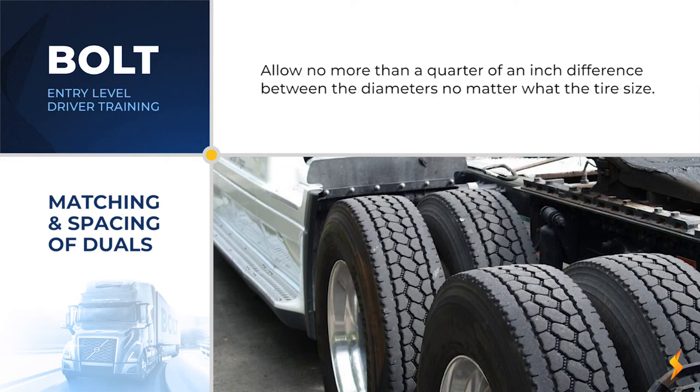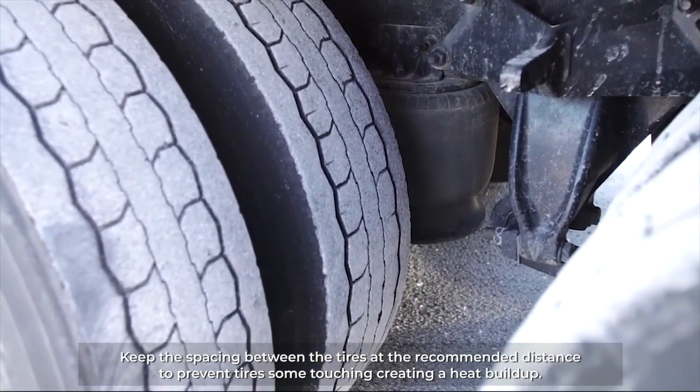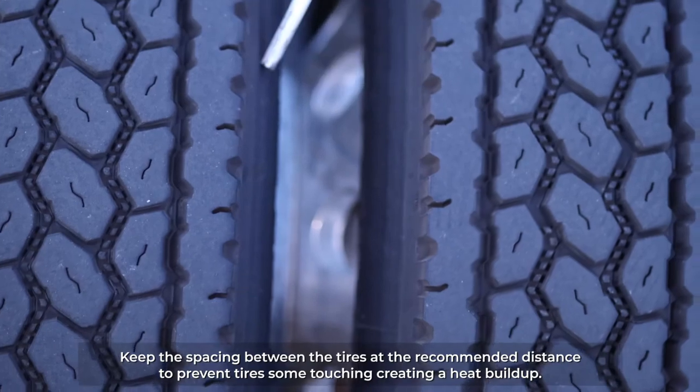To be on the safe side, allow no more than 1/4 of an inch difference between the diameters, no matter what the tire size. Also, keep the spacing between the tires at the recommended distance to prevent the tires from touching, creating a heat buildup.